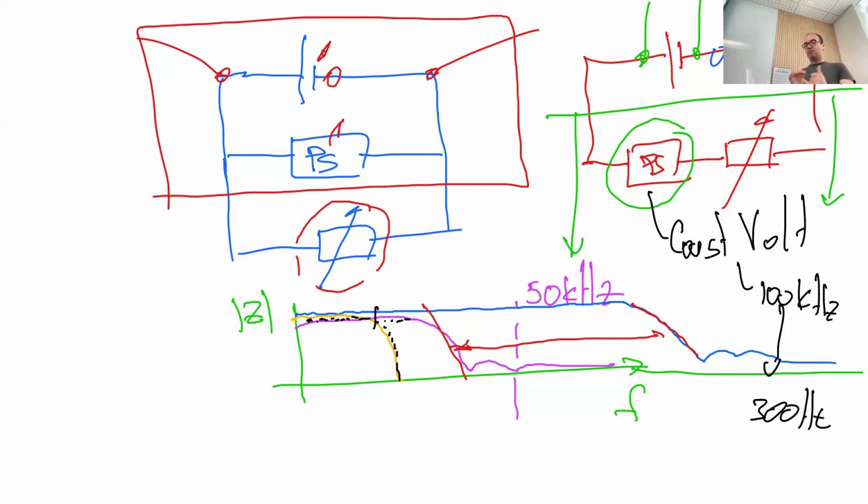So that is why we always take great care of these bandwidths, because although we are measuring voltage here, it is physically impossible to detach the influence of the other part of the circuit. The other part of the circuit is present. The only thing we can design is to make the other part of the circuit with so high a frequency band that it doesn't influence the frequency response of the fuel cell. This is the only thing you have to take care of.